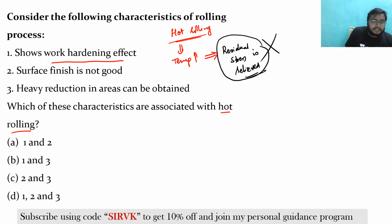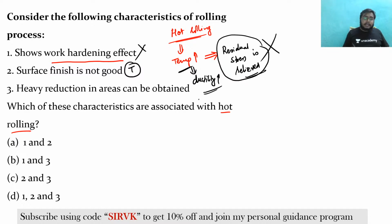Now see, surface finish is not good. Yes, it is true. Heavy reduction in areas can be obtained. Very good. See, if in hot rolling the temperature is increased, the material will have more flowability, that is, ductility will be more. So if ductility is more, can I say that heavy reduction can be possible? So it is also true. So what I can say here is that statements 2 and 3 are true and 1 is wrong. So where is it? Is it C? Yes, it is C.